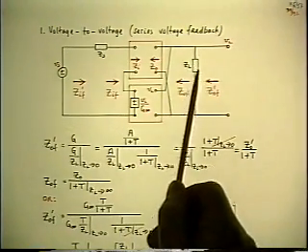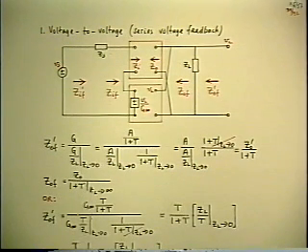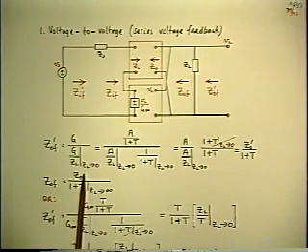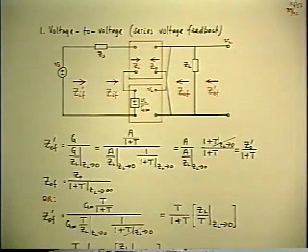But when you let ZL go to infinity, it gets bigger. Therefore, the T gets bigger if you take that limit. You can't say how much bigger, but bigger. So the conclusion is the inside output impedance with feedback is equal to the inside output impedance before feedback divided by a factor which is bigger than F. You get a bigger reduction factor. That's not such a well-known result. Well, that's two answers in a very short space with very little algebra.